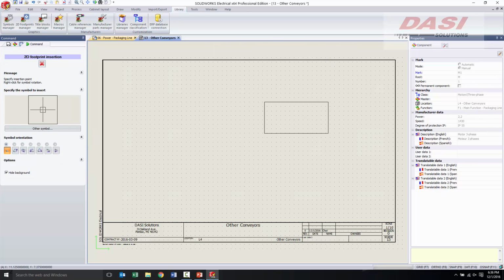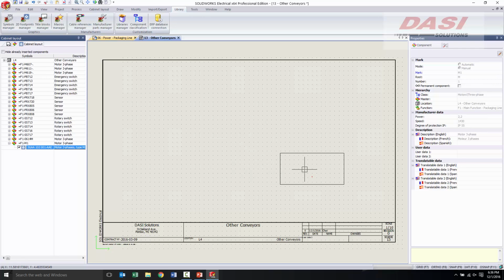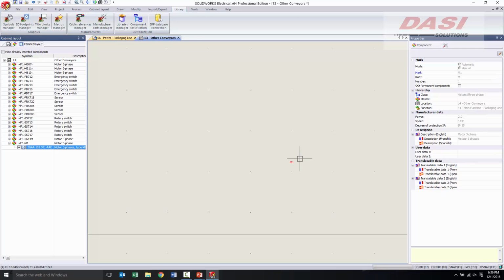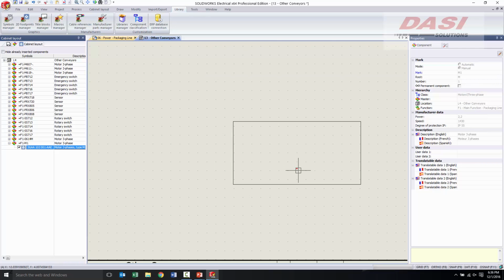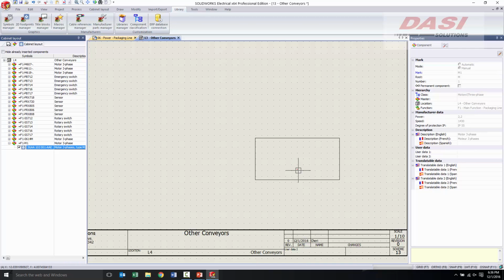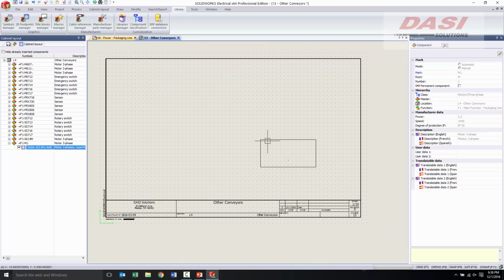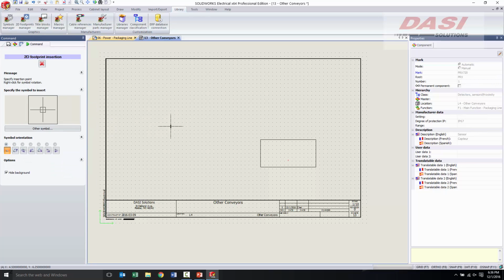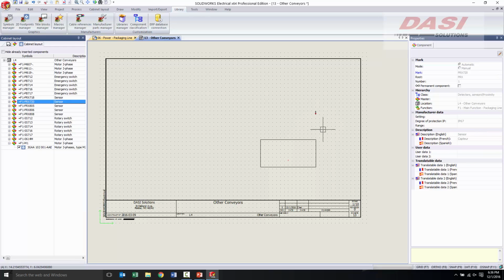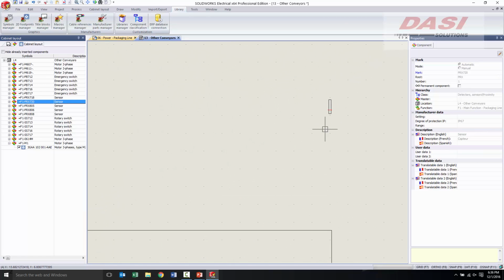Right, so now when I go to insert this part, notice I have a motor that is the correct size, and I would place this on my conveyor somewhere. Right now I haven't adjusted it, so the tag is small compared to that, because it's a very large motor. But we're doing a 1 to 10 scale. If I were looking at a prox, maybe this prox here, there's the size of a standard prox, and it's actually giving you that prox. So you're building from that library. All you're having to do is create some dimensions, and it's going to start giving you realistic architecture for where the real estate is being used.